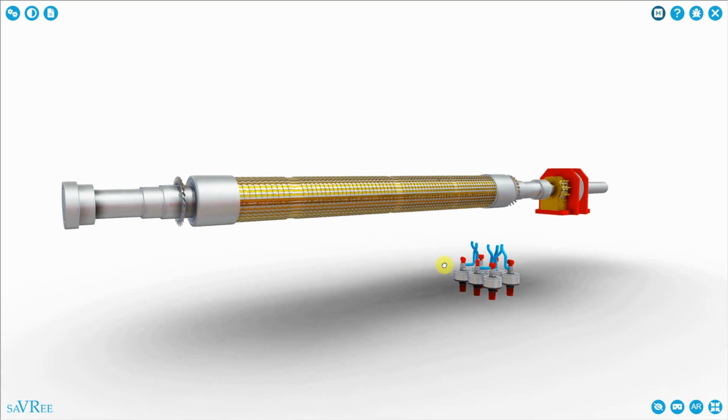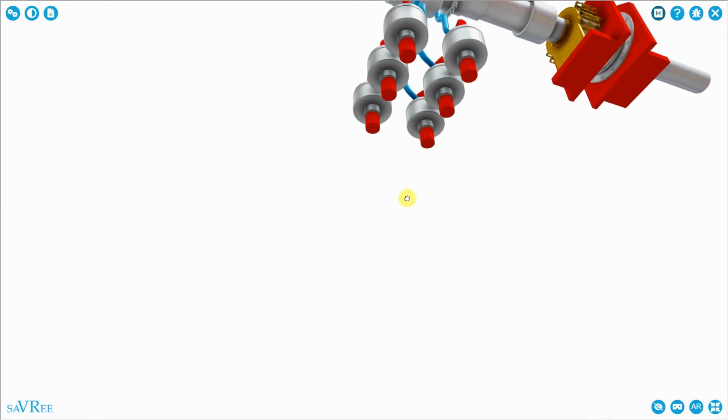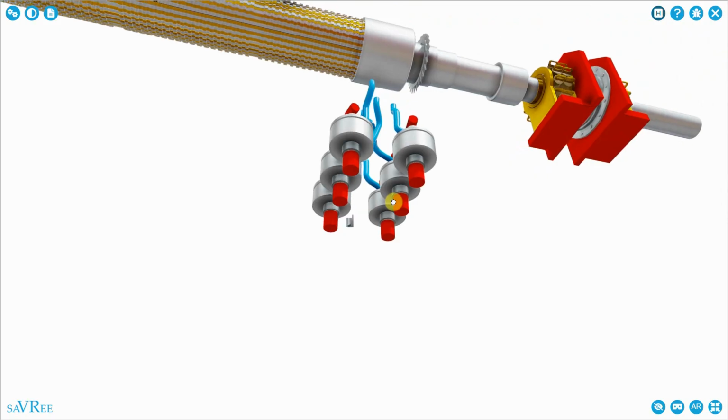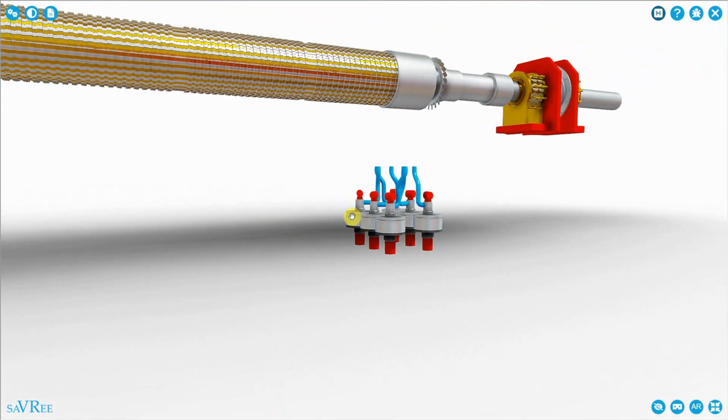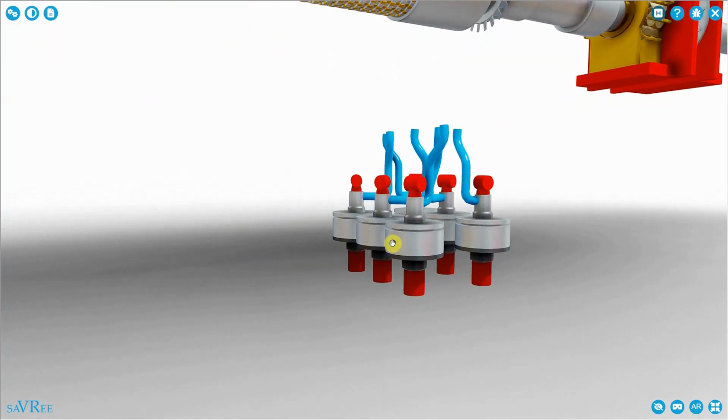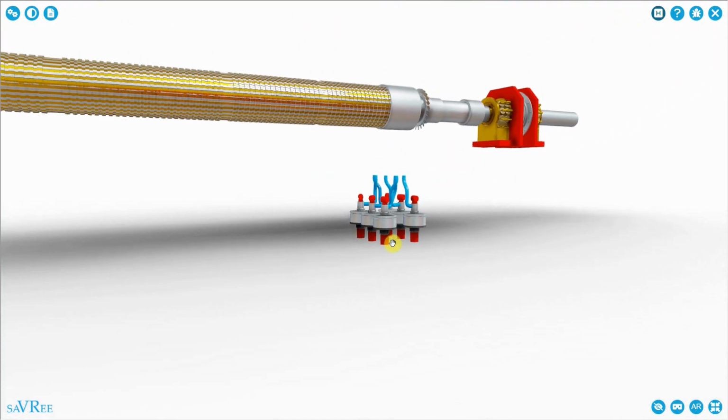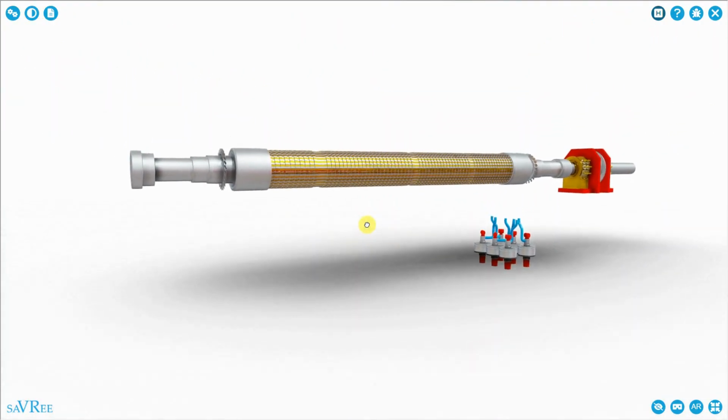We're producing 3-phase power, although there are 6 connections here. This is because there are 3 phases going in, 3 phases coming out, and the generator is connected in star. So don't be fooled, this is not a 6-phase generator, it is a 3-phase generator.